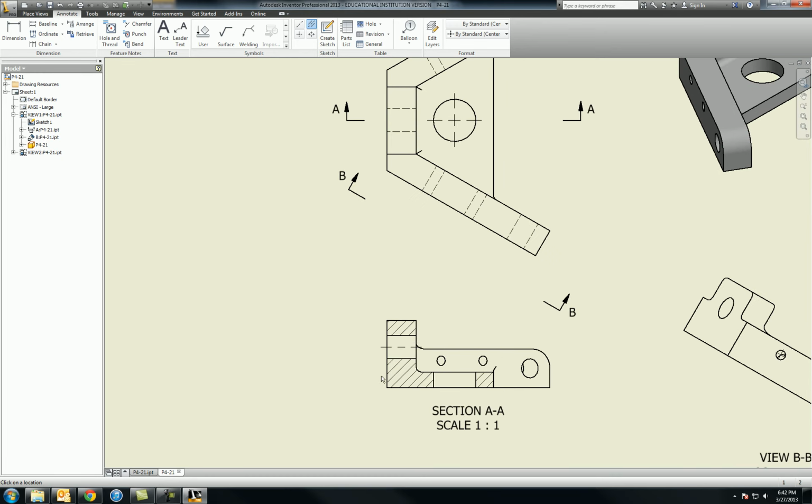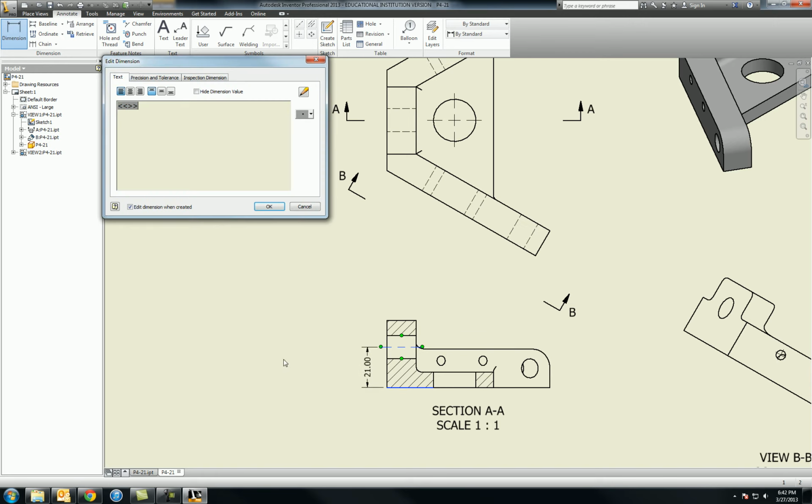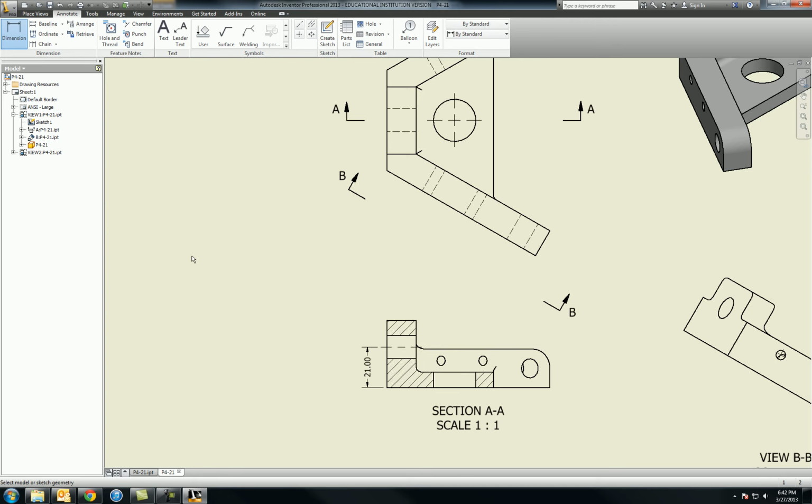So at this point I'm going to start my dimensioning process. First things first, I want to go from the center line to this point. That's going to be 21. The way it is in the book is 13 up from the top of the base, which is 8 thick. That's a really nasty way to dimension this thing. This 21 is going to be a lot easier to lay out when somebody actually has to go to cut that hole. My next dimension that I'm going to place is going to be the 35.